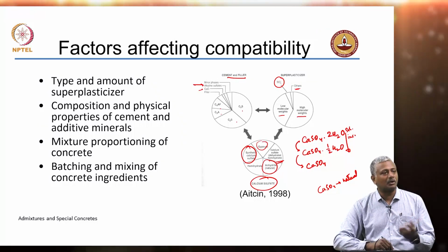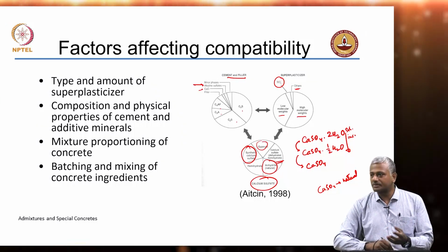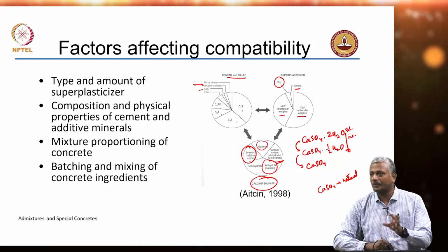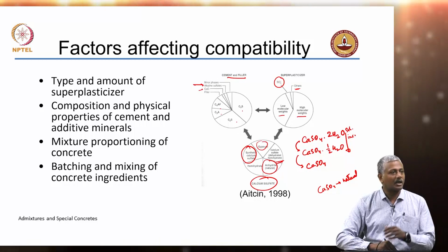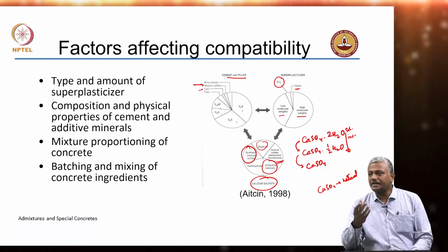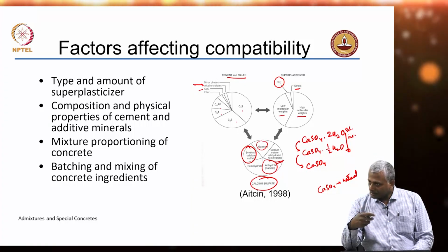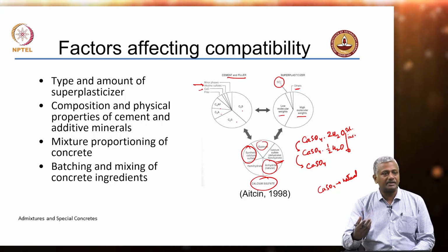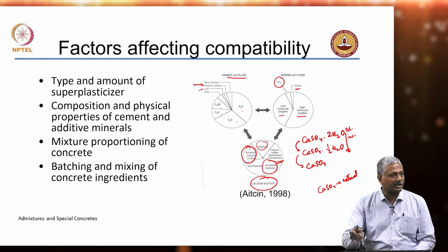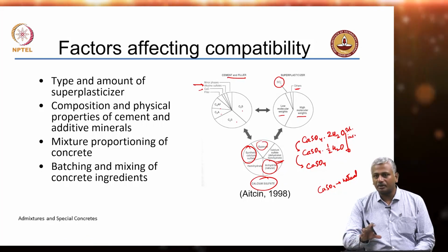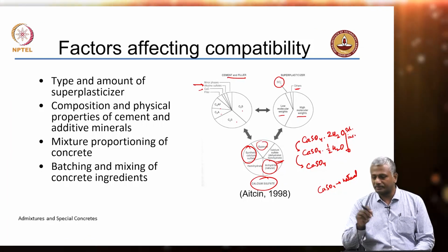So, generally what you will see is in most cements there will be a judicious blend of the different types of sulfates. Now, what happens is when you grind the cement, the heat generated because of grinding, if it is excessive, it can also have a tendency to convert gypsum into other hydrated forms of calcium sulfate, but you want some sort of a combination of these. Okay.